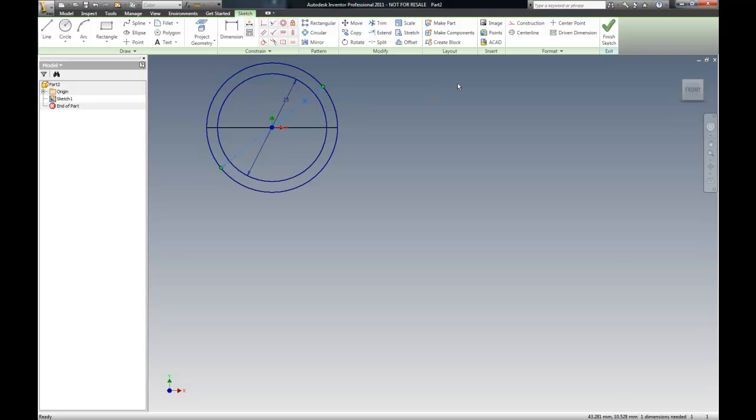So I'm going to grab this line, I'm going to pick that line, and turn that line into a construction line. I'm going to go to my friend offset, which is right over there, and pick it and drag it down here. Escape several times, go into my dimension, pick that point there and come right over here, pick, and I believe the distance on that is 25.